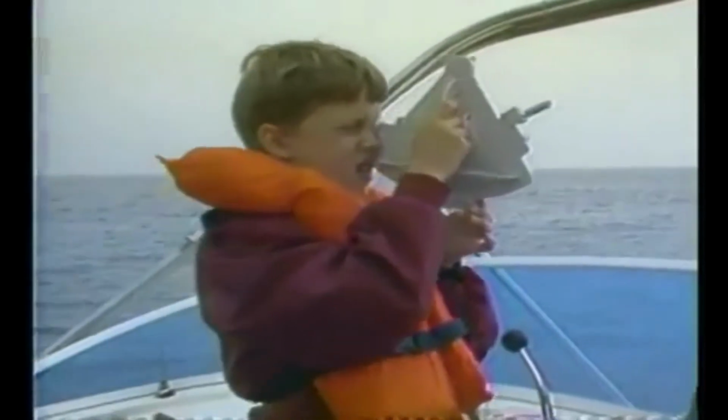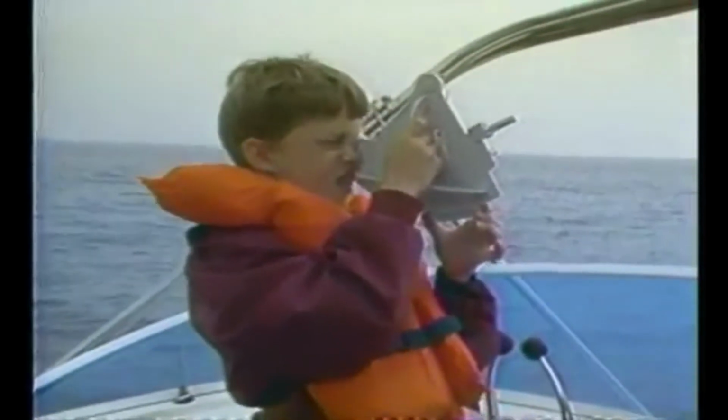And then he tells you what to do with all the readings, how to fill out the worksheet to do a noon shot. That's just the sun. And it doesn't mean 12 o'clock watch time necessarily. It means local apparent noon when the sun is directly above your meridian, that precise second. You use the sextant to get the measurement, find out when it's right above you, and mark the exact second.